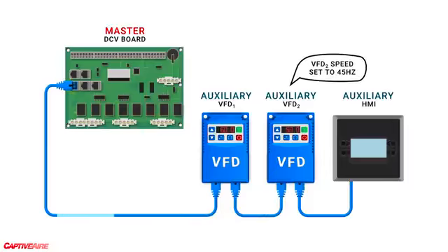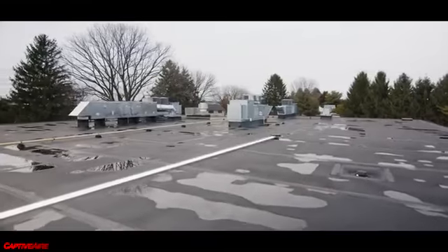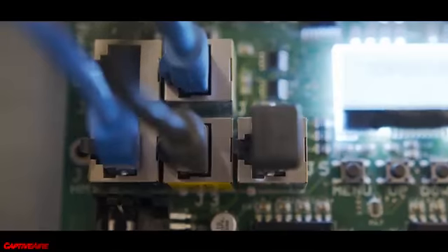Since we can daisy chain several devices onto the same wiring, this exchange happens with only one auxiliary device at a time, which makes Modbus relatively slow. There are faster protocols, of course, but Modbus has good benefits. You could run really long cable links. If you have something on the whole other side of the building, you can just run Ethernet cords, which is just so nice.